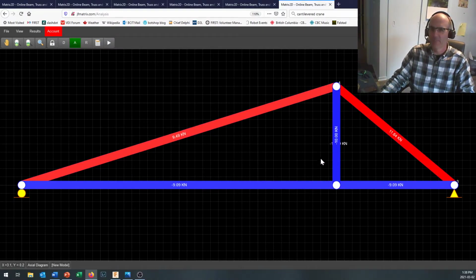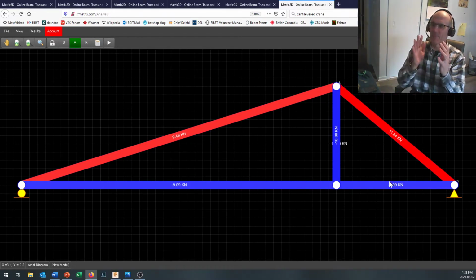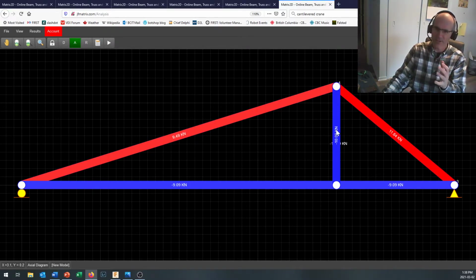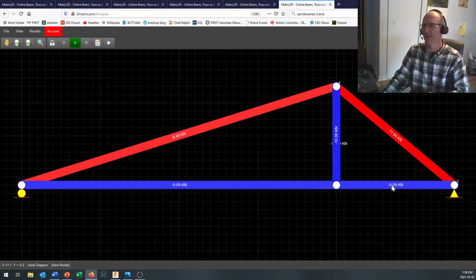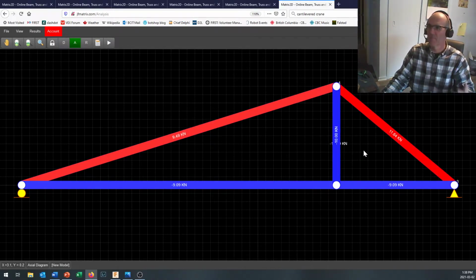Okay, but because we made this taller, now we should see a slightly reduced force in compression right here, since this member is taller, this side of the triangle is taller. So when we're calculating our horizontal component of the vector, and you can see the horizontal number appearing right down here, since this side is taller, our 10 newtons relative to that side will result in a smaller number right down here. Okay, in other words, we're minimizing the effect of the horizontal component.